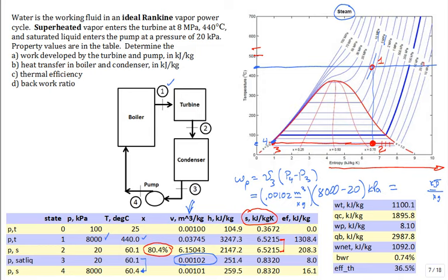Let me repeat that. A meter cubed times a kilopascal, chase your units, do this a few times, convince yourself it's precisely 1 kilojoule. Do I have to memorize that, Professor? Well, some things are really nice to know when you want to take a test and it's timed, right? Work that out, develop confidence, and use it.